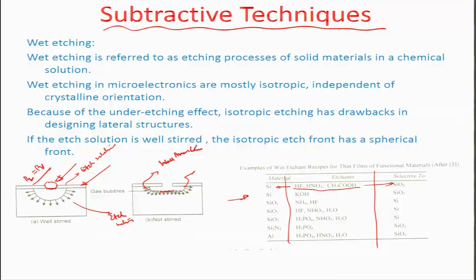That means this particular area, which is subjected to the etch, let us call it the flat area, would have more etching, and if you are not having a removal mechanism, it is going to accumulate the etched out particles and create a concentration around the flat, because of which further movement of the etchant towards the flat may be severely limited, and there may be a case of under etching or lateral etching, which produces an undercut. So, an undercut typically would happen because of lateral etching.